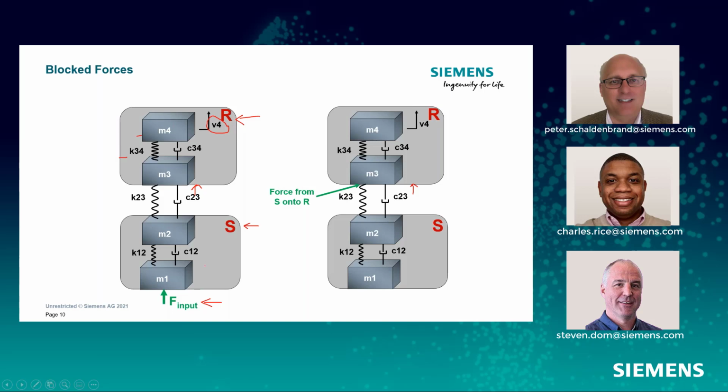Yep. And what's interesting, in these techniques like transfer path analysis, we try and determine the biggest paths of a system. And we never actually get around to measuring this force input. It's so hard to do. You'd have to have a combustion engine. You'd have to have pressure traces of all the cylinders and be able to translate that to the inertial loads that it creates and forces.